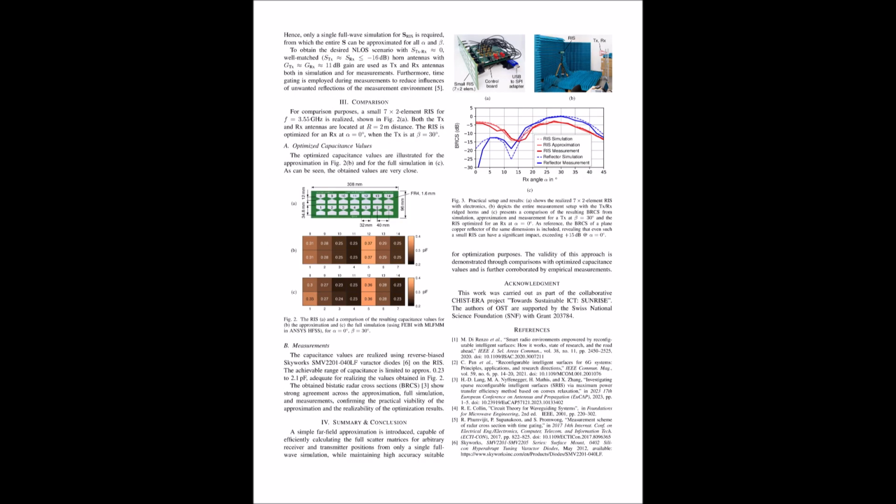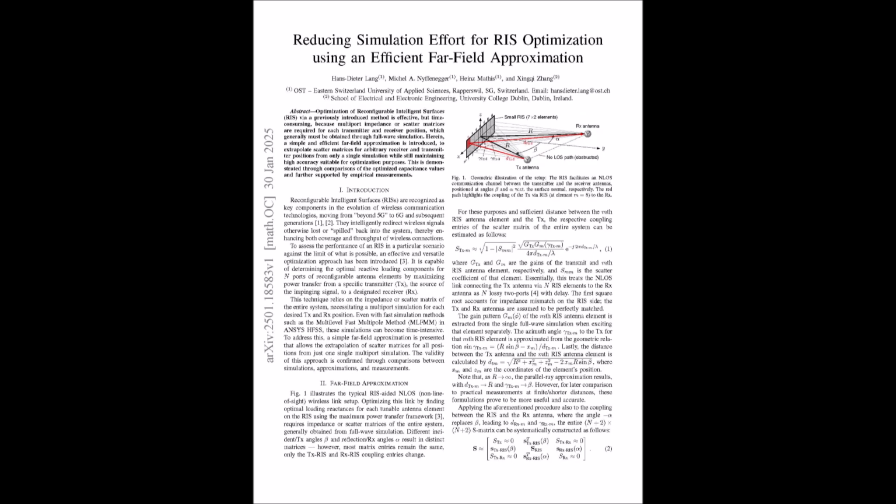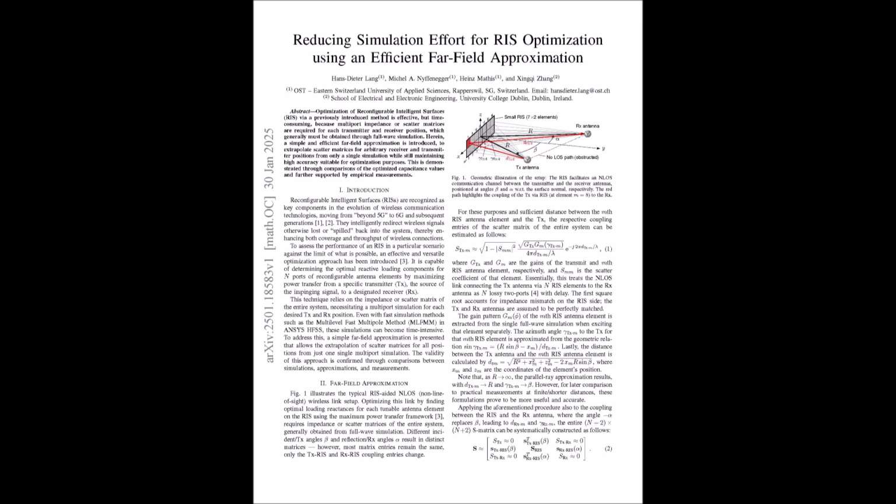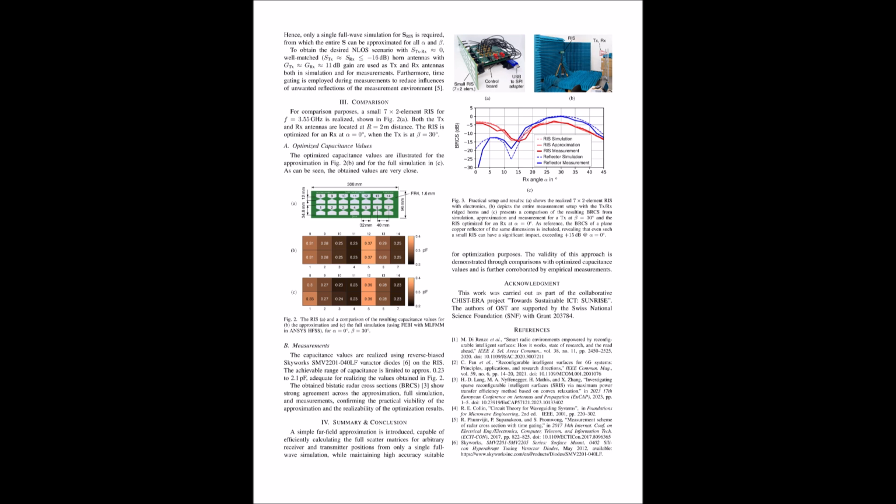But let's get real for a sec. The material you sent over, all this research on RIS optimization, it gets pretty heavy into the math, right? Yeah, optimizing these surfaces is no walk in the park. It involves a lot of complex calculations, especially when it comes to simulating how they behave in different scenarios. But that's what makes this particular research so exciting. Oh, okay. Why is that? Well, it proposes a really clever technique, a way to streamline those complex calculations using something called far-field approximation. It's a way to make the optimization process much more efficient without sacrificing accuracy.